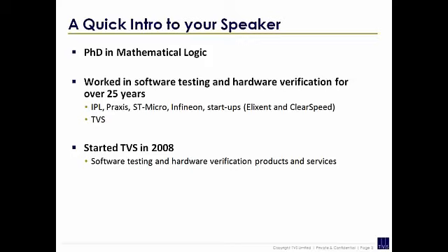And then these two are ASIC companies where we were doing a lot of hardware verification, and a lot of the techniques and practices which we talk about tonight come from an ASIC environment rather than an FPGA environment. Most avionics companies are working within FPGA rather than ASIC. But ASIC verification techniques are a long way ahead of FPGA verification techniques. Most of these advanced techniques have been deployed in ASIC for a very long time. So they're very mature techniques that just haven't really impacted avionics yet. And one of the reasons is how do you get compliance as well as those advanced verification techniques.